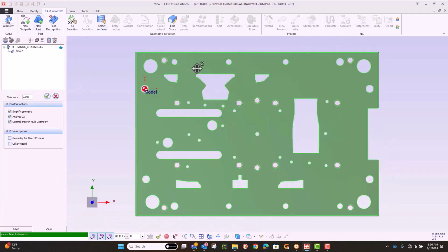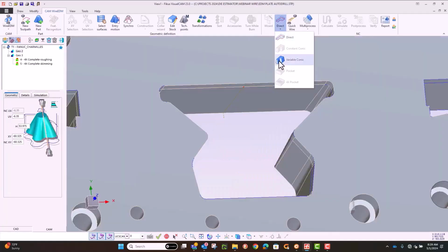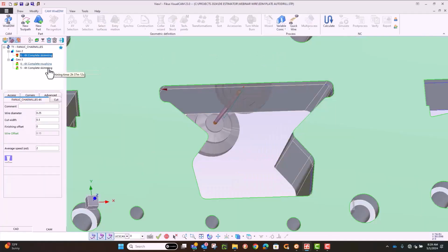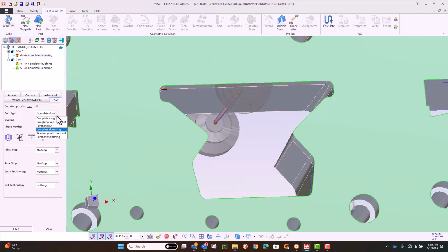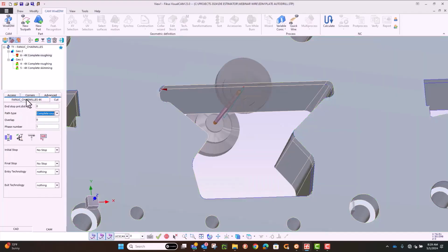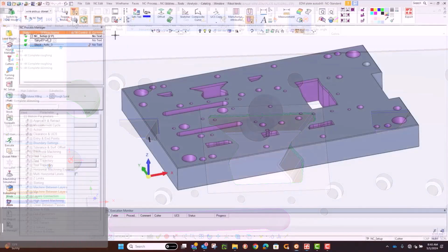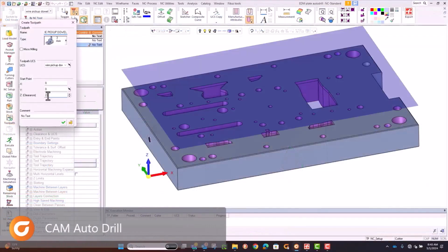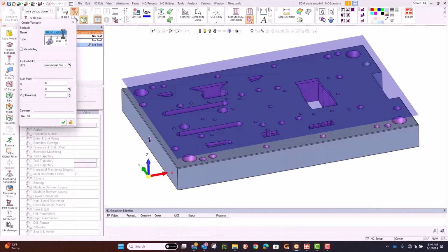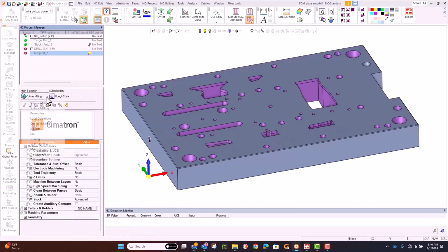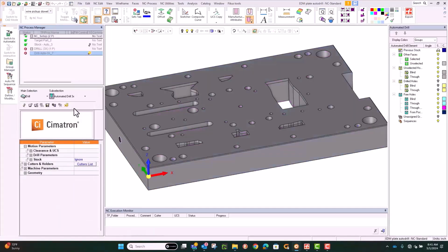Another big part of doing a die is, of course, a wire EDM when it comes to those punch holes. Here at our wire EDM, I'm going to set up one of these punches. I just identify that feature area. It's going to be a variable, or in this case, 4-axis cut. We'll tell it what we want to start with. I'm going to rough cut through the tapered area, then come back, do another rough cut on the land, finally come back with a finish cut along the land. So very quickly, that also can be saved as a sequence or template and used again.